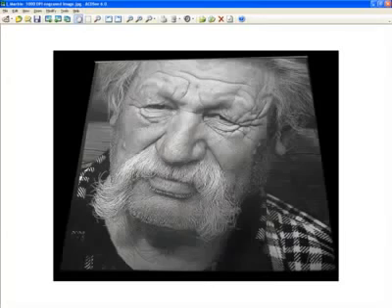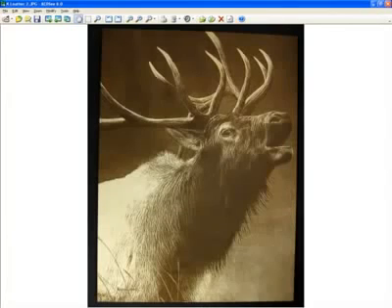Now, if you want the absolute best results, the high density or HPDFO lens is preferred for best photography-type engraving. But a 1.5 is the next best, followed by the 2.0, all of which can be done. Most of the samples I will run are run on a 2-inch lens just to show you that it can be done. For example, this nice leather picture was done with a 2-inch lens, no problem.